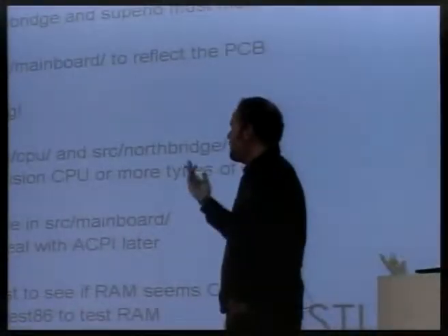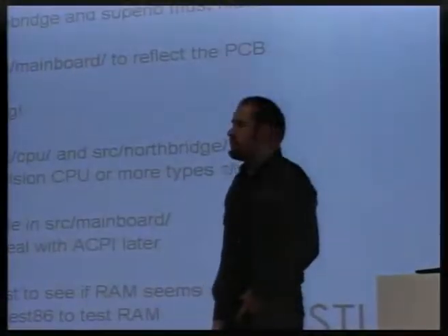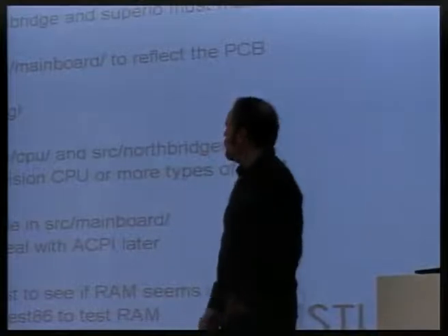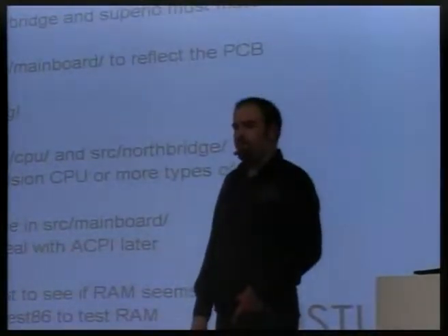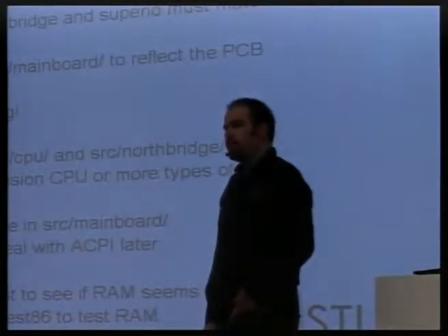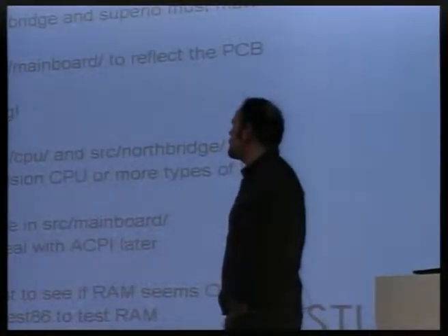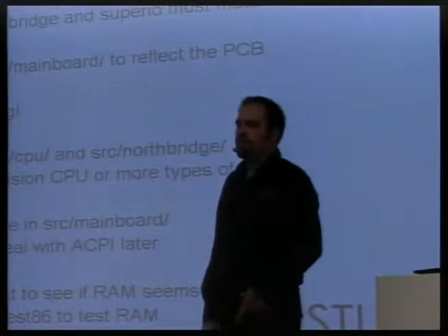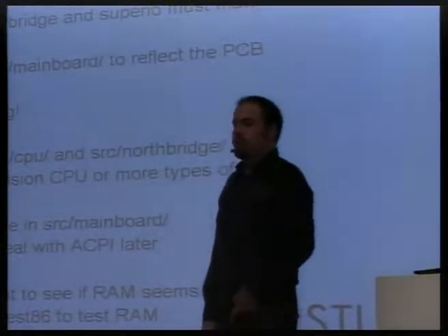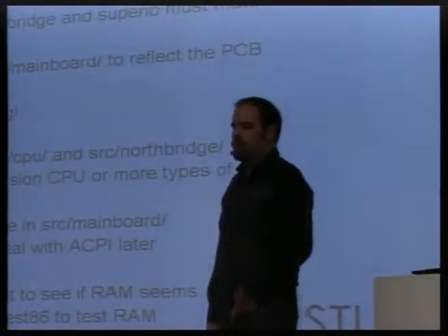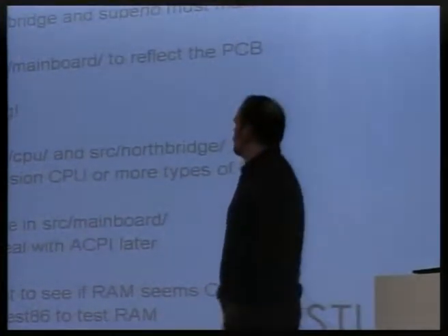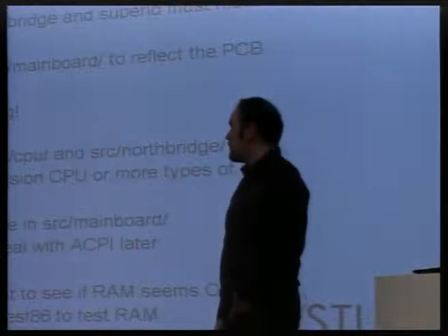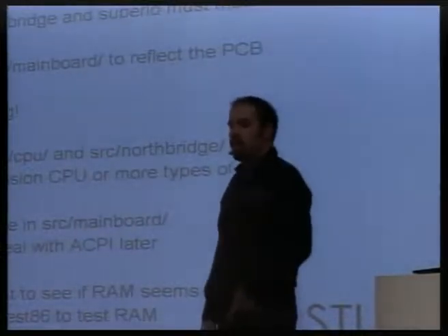So for this to have any sort of chance at success, you need the CPU and the North Bridge and the South Bridge and the Super I/O to really be the same as the other board. But many times they are, because all the vendors have reference designs, and many mainboard designs are really just copies of the reference design with a few small variations. And that means you can get lucky, and it's really easy to add a new board.